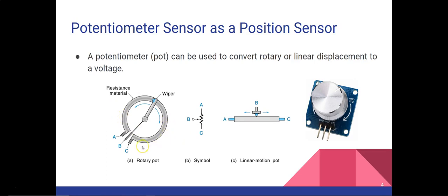Now the potentiometer sensor just described is the single-turn type sensor, which has only about 350 degrees of useful range. You can see here this is not forming a 360. There is a little portion which is going into these three leads, so that's why we say this will have around 350 degrees of range. This potentiometer sensor is similar to this one. These are the 3 leads, and the rest is the range.